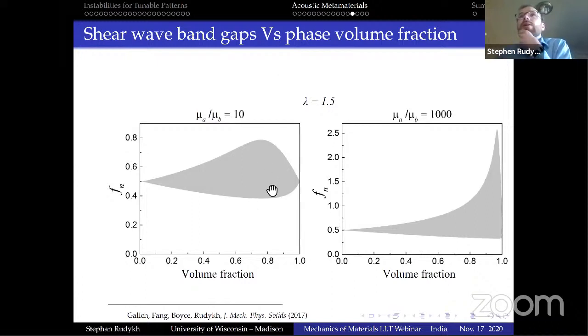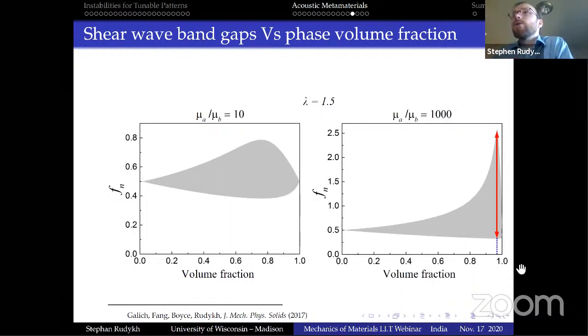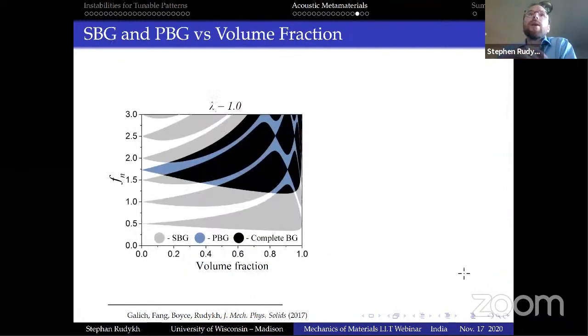So, for example, I'm taking the low band gap for different contrast and stiffness composites, and then you can find a particular situation when, instead of something very tiny and almost negligible band gap, you can maximize and obtain a very large band gap if you choose the configuration of your material well, and then you can tune it even more with deformation. The tunability looks like that. Okay, so these are your band gaps, and for different volume fractions you can create this map.